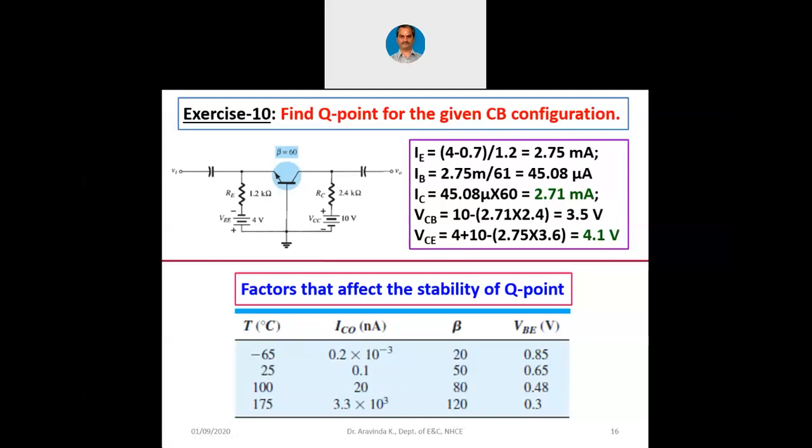Always in any semiconductor, there are majority carriers and there are minority carriers. Always there will be minority carriers, and even the minority carriers contribute to the electric current. As a transistor is nothing but 2 PN junctions, base to collector and base to emitter, even in a transistor the reverse saturation current comes into picture, because even in an N-type region, there can be holes.